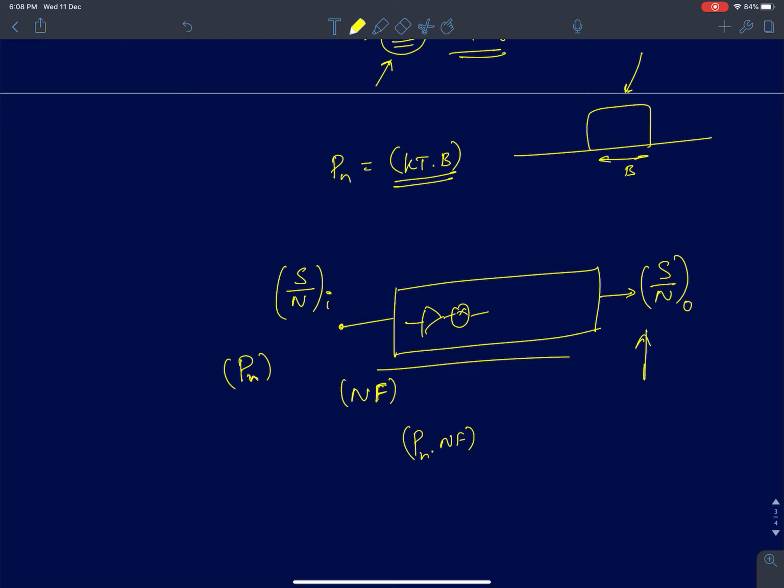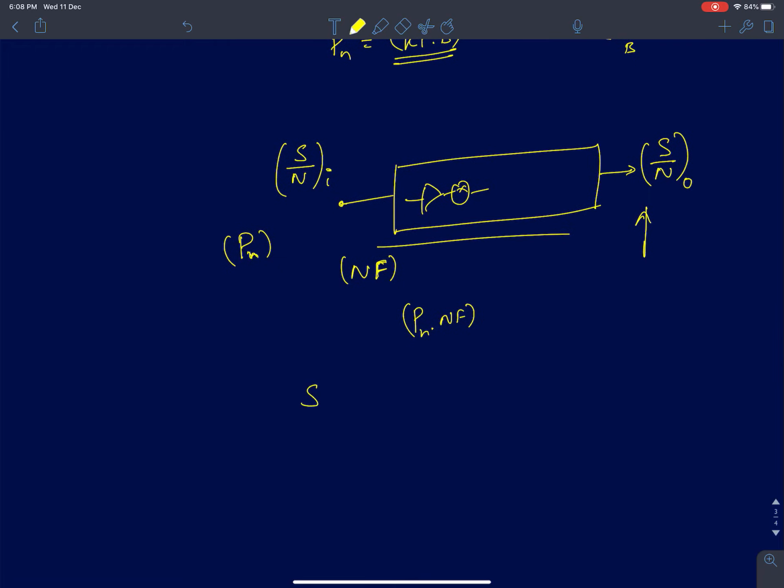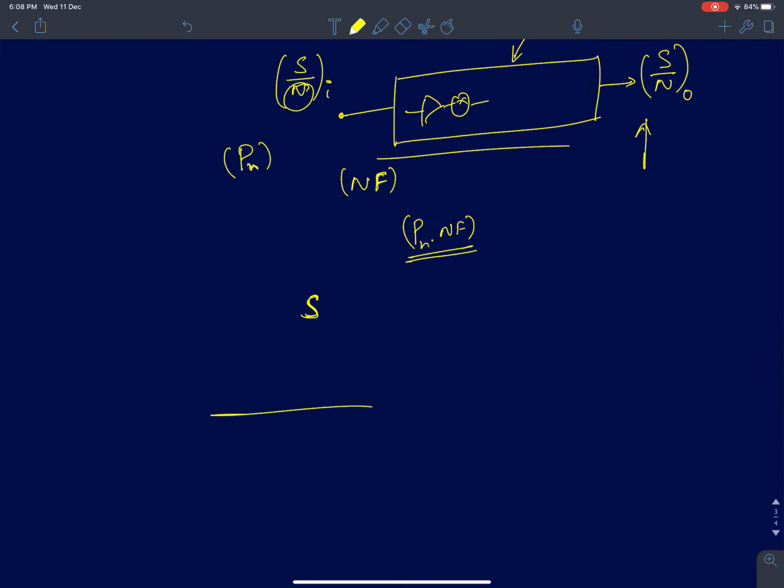Okay, so it sounds quite intuitive because, for example, noise figure captures the noise added by this stage. It also includes the noise at the input N. It tells you by how much the noise had actually increased at the output. Therefore, I will show it graphically. So let's say kT is the available noise power, you multiply it by B, this is noise power per hertz, multiplied by B, you will get total noise power.